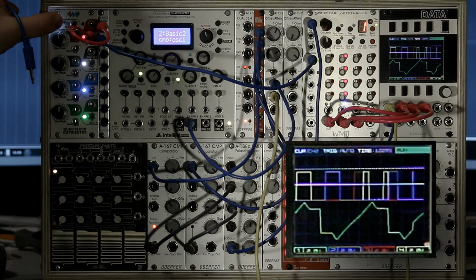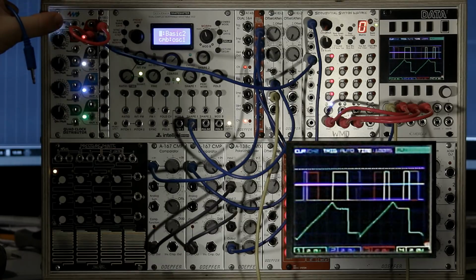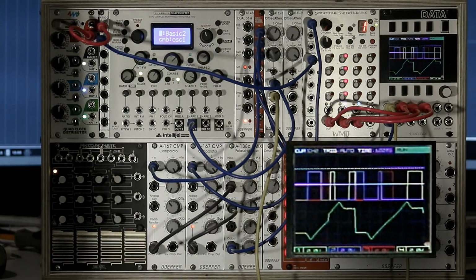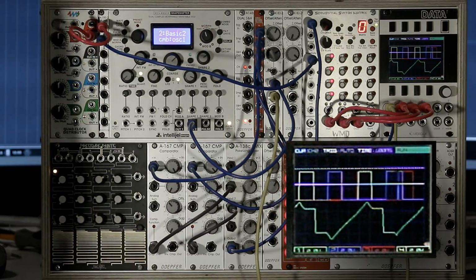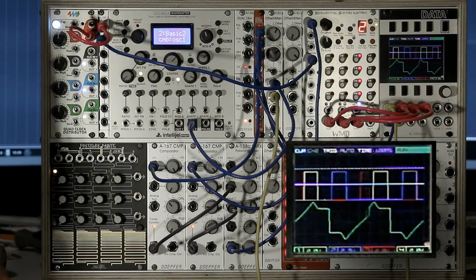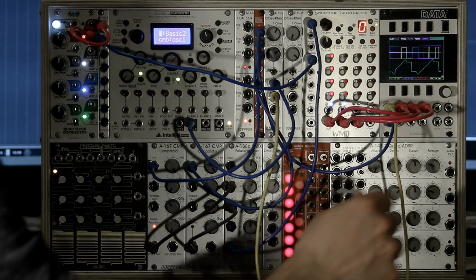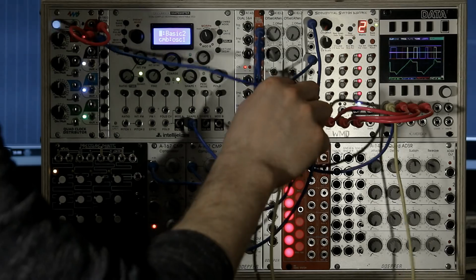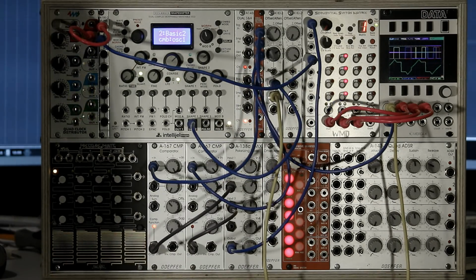Looking at the data display, you can see some problems appearing. Some clock gates are cut and split into different outputs. This is because our main LFO will often switch comparator states during the clock gate. Since we will play our melody at some tempo, we can easily fix this by sampling the main LFO signal at that clock rate. We just need to run our main signal through a sample and hold module.